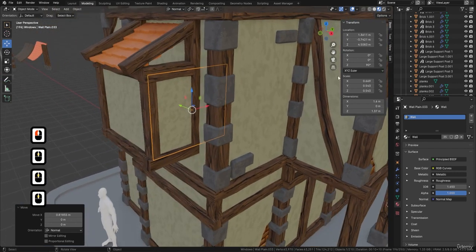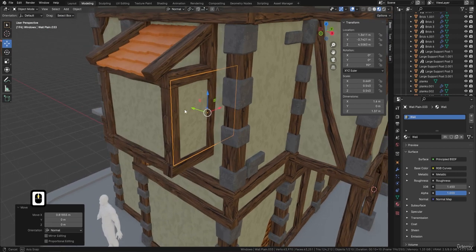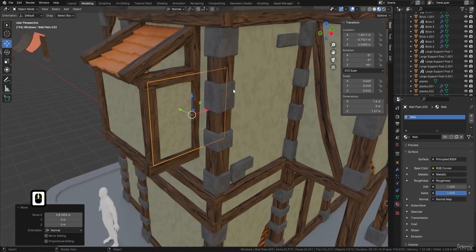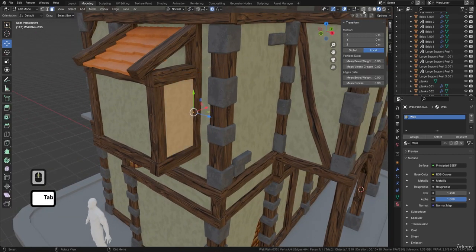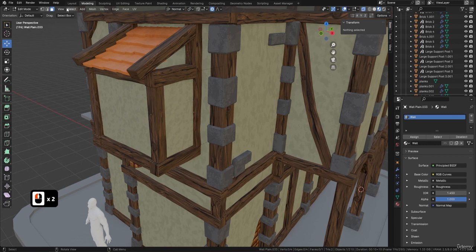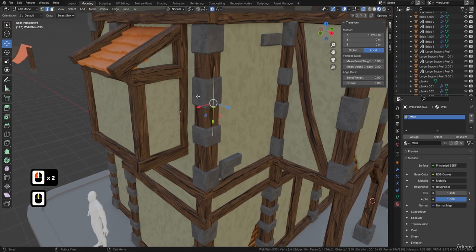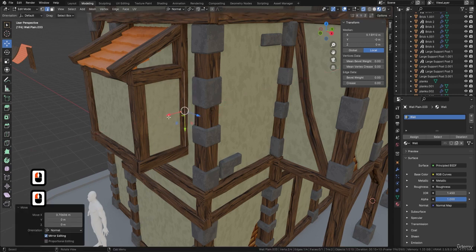I'm probably going to come in as well because I hate wasted UV. All of this in the back of here would be wasted UV, so it's important that we don't waste too much UV, because even though we're using seamless textures, it's still part of the render, you know, it being back here, so it still costs a little tiny bit of something, but those little bits of something actually add up. So what I'm going to do is come, edge select, grab this edge, pull it back without proportional editing on, like so.